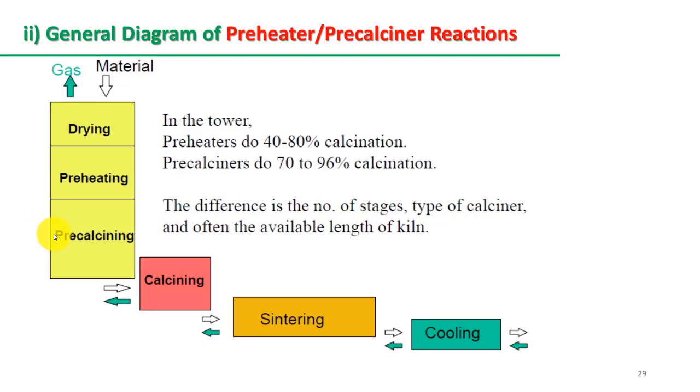Like you have calcium oxide, the decomposition of calcium carbonate occurring at calcination, precalcination. In calcination, you have other products formed like the decomposition of aluminosilicates into the alumina and silica constituents, which afterwards go into the sintering process, at which the tricalcium silicate, dicalcium silicate, tetracalcium aluminate, tricalcium aluminates and tetracalcium aluminoferrites are formed at the sintering stage. After the sintering, clinker is formed, then cooling is allowed for a sufficient time so that it can be ground afterwards by the addition of gypsum.